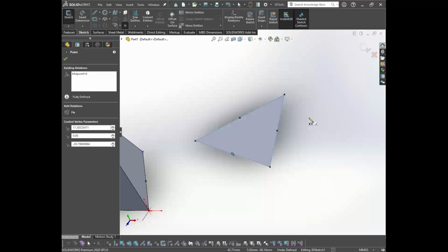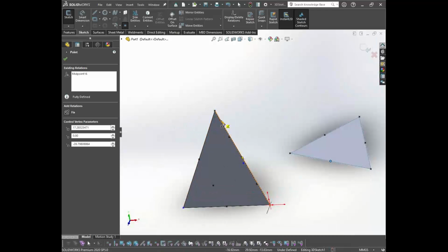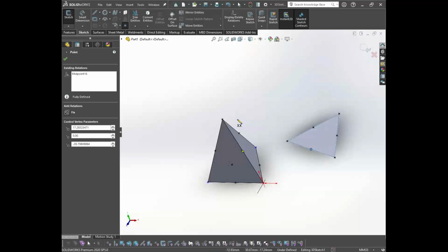Why we use this particular concept in FEA: there are certain small fillets involved in my geometry that I need to capture more properly. If I introduce more elements, more of the geometry will be captured in my analysis, and I may get results closer to the actual values. The more elements you introduce, the more accurate your results are going to be. But at the same time, since your degrees of freedom are increasing, your solver time may increase drastically.